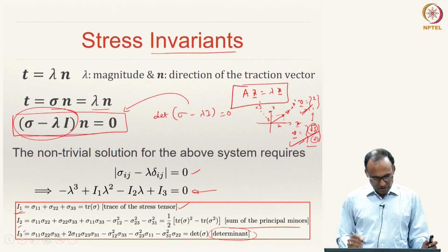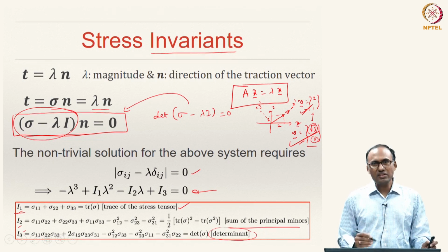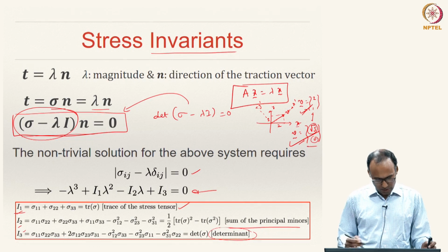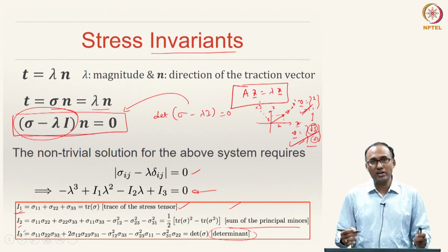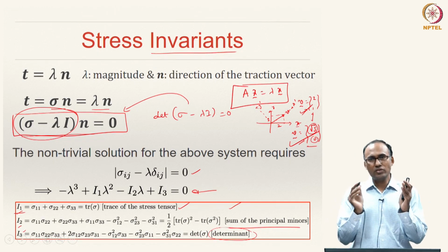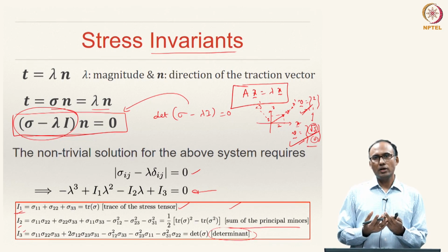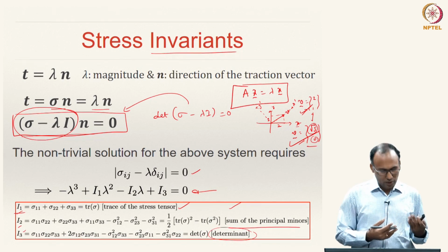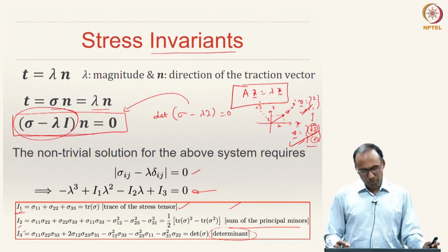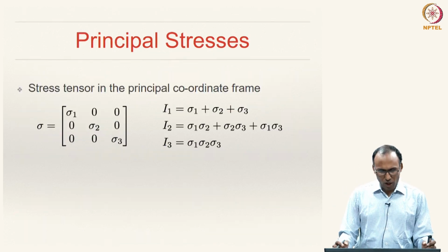This is what we mean by stress invariants, and we will use them in the failure theories, which is why we are introducing the concept. Whether you work with the full stress tensor or the principal stress tensor, you can write your failure theories in terms of these invariants, I1, I2, I3, or in terms of principal stresses. Alright.